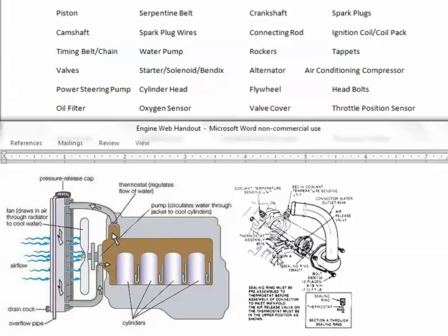Your water pump, of course, then is also going to be forcing water through the system if the thermostat's open. So the water pump, you can link to the thermostat. Your thermostat is located in the thermostat housing, which we'll get to in a minute.